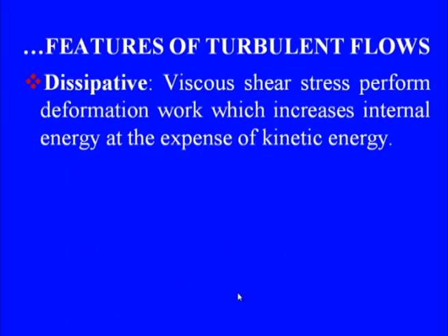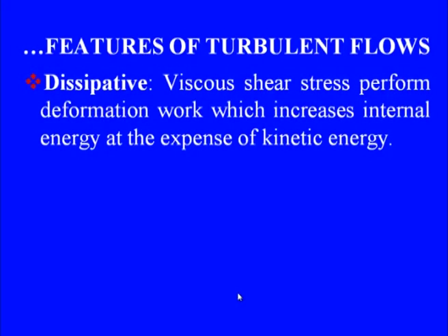The next most important feature is dissipation. Turbulent flows are always dissipative, and this dissipation comes up because of the viscous action. Now, this is sort of a dichotomy here. We would say that turbulence occurs at high Reynolds number. At high Reynolds number, viscous effects are fairly small compared to the inertial effects, but the losses in turbulent flows, or dissipation, loss of energy, occur because of the viscous shear stress. In fact, this dissipation is entirely due to the action of viscosity. So, these viscous shear stresses perform deformation work which increases internal energy at the expense of the kinetic energy of the fluid,